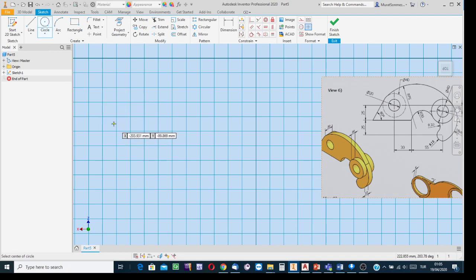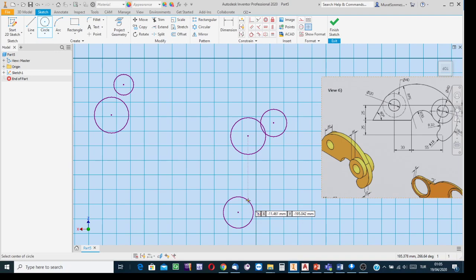Click on this button, and then I'm going to create a circle here arbitrarily, and then one more circle. In Inventor, avoid having dotted lines between the cursor and the characteristic points. If one exists, escape from that positioning. Okay, 2 circles. Well, at a lower level, 2 more circles. Arbitrarily create them, avoiding dotted lines. And then here, 1 more circle.